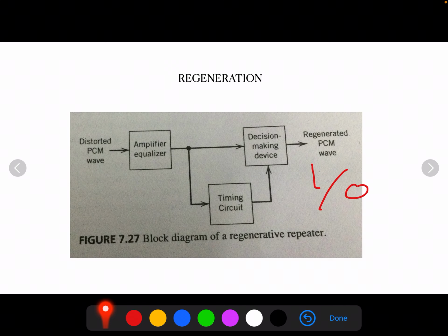One is the unavoidable presence of channel noise and interference, which causes the repeater to make wrong decisions occasionally, thereby introducing bit errors into the regenerated signal. Second, if the spacing between two pulses deviates from its assigned value, a jitter is introduced into the regenerated pulse position, thereby causing distortion.